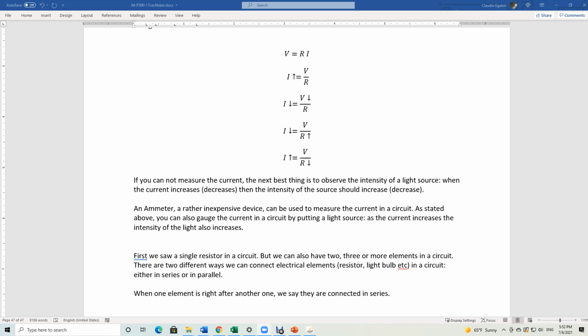Here you go, one resistor, and I'm going to connect another resistor, a second resistor. How do we connect them in series? We touch one end to the other one, like that. And what else? I have to close the circuit. I gotta connect this to the other end of the battery, by connecting them in the same row. Right now the circuit is open and there is no current passing through it. However, if I touch this end of the resistor to the other end of the resistor, now we have a closed circuit with two elements in series.